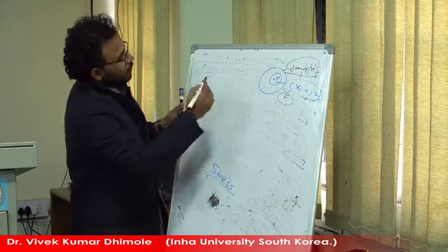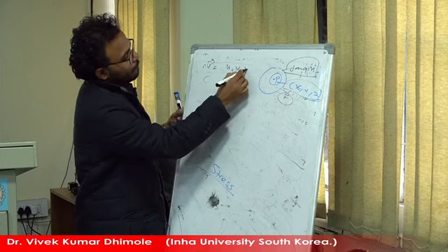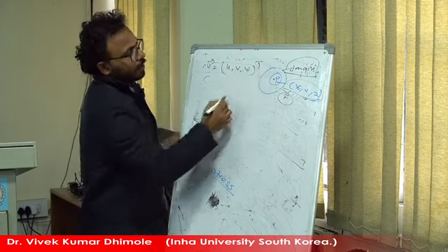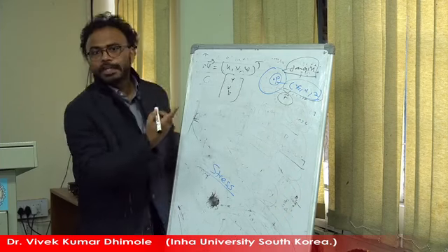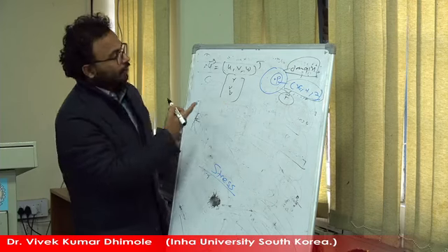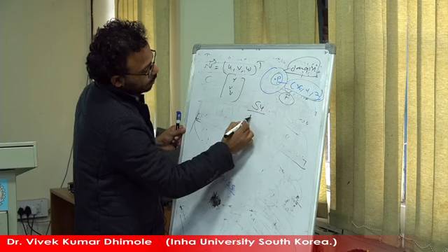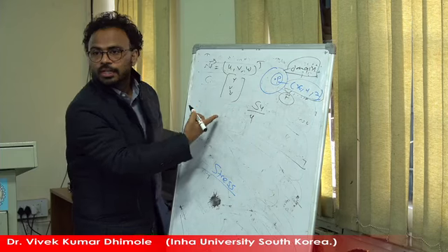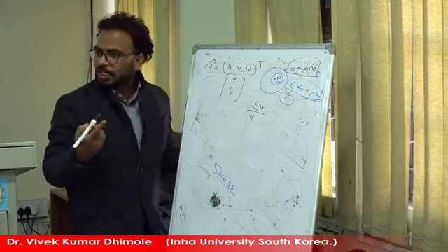Apply the force. Suppose the deformation vector, the U vector, is U, V, W. Transpose means column vector, U, V, W. When you apply the force, it will deform, right? So this is the deformation U, V, W. When the deformation is done, what is the strain? Change in length upon original length, right? There will be strain when it deforms. Change in length upon original length in the X direction, Y direction, Z direction, and shear strain, right?